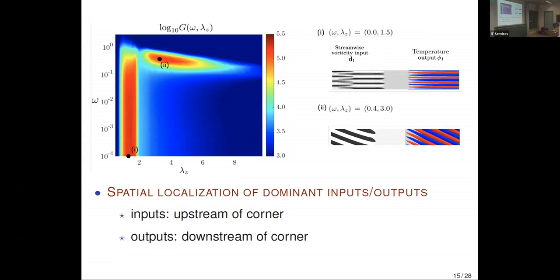And there is another region here, which is taking place at order of 1 values of temporal frequency and lambda z as well. So this region here is associated with streamwise streaks, which are roughly steady, and this region here is associated with oblique modes, right? And the length scale of oblique modes here is roughly twice the length scale of the underlying streaks.